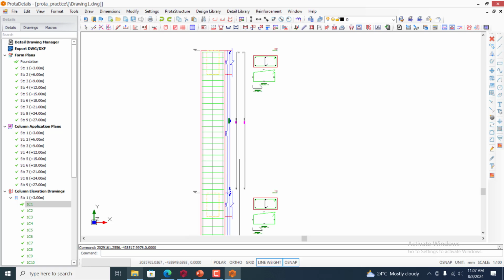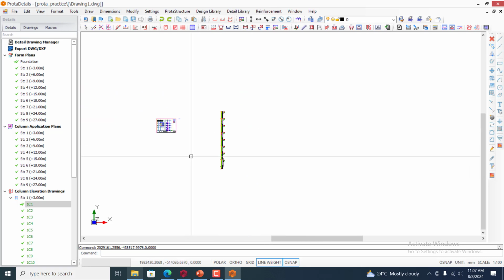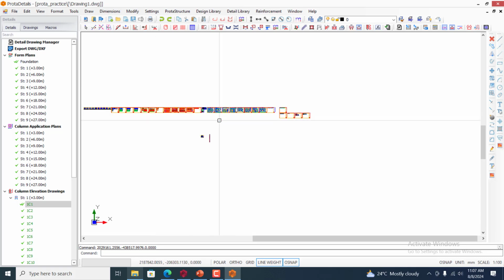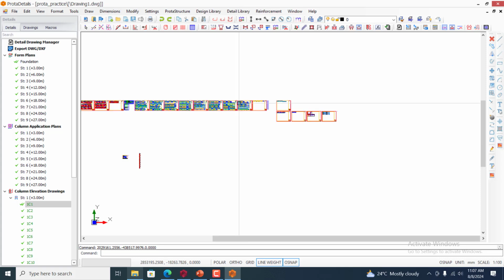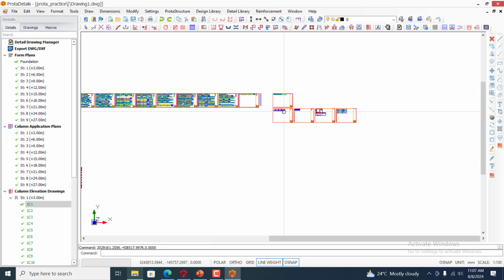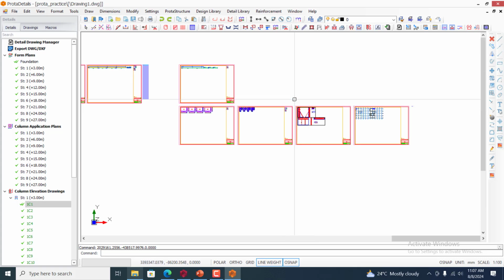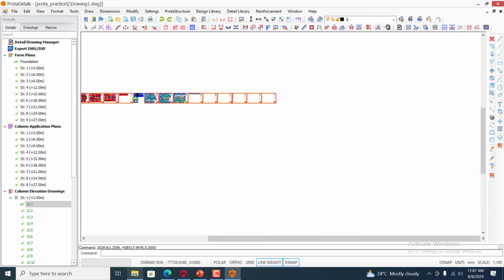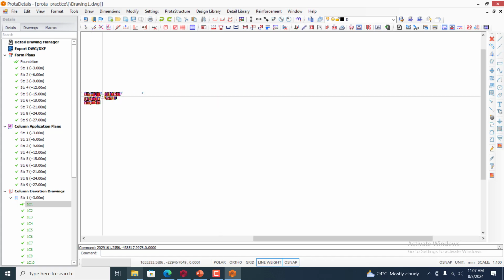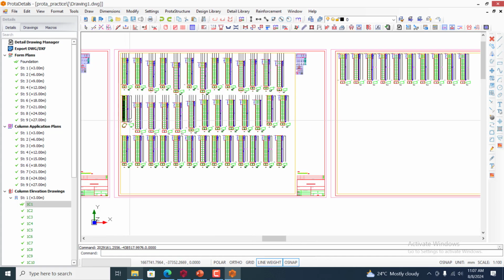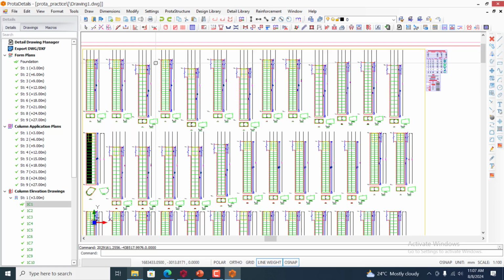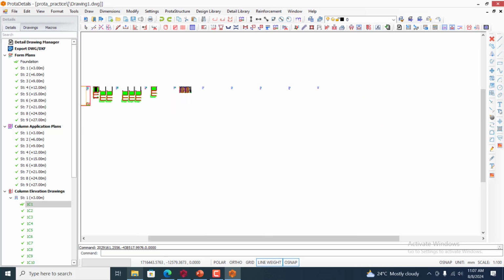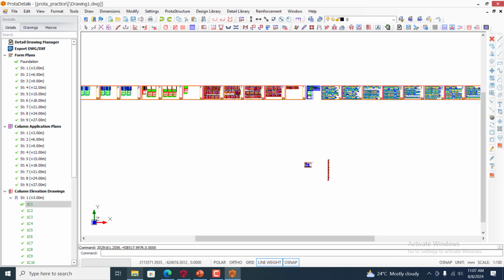It's very important that this is represented this way. But you can compare this with this, you will notice that there is a difference. For this one that was generated automatically, you will realize that the software had to break the columns at each floor. Okay, but I just want to show you that the software has the capacity of generating your columns all through your stories. So you can see this is at each level, and it's not a very good way for me to represent my column.